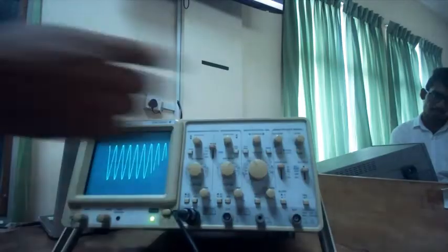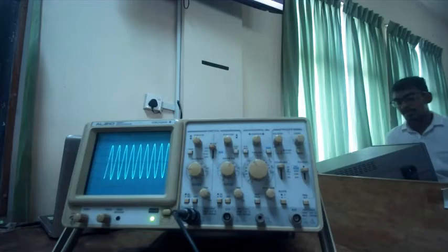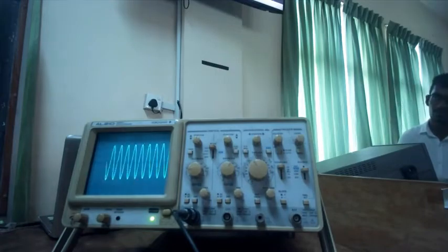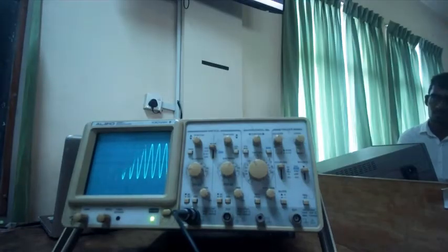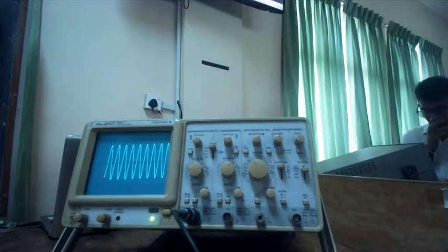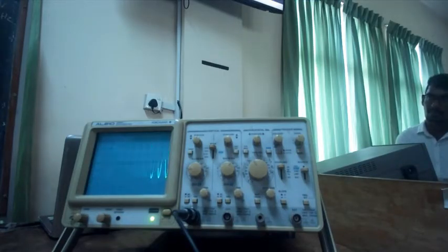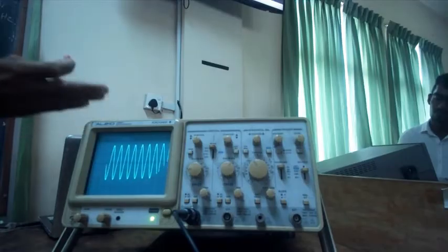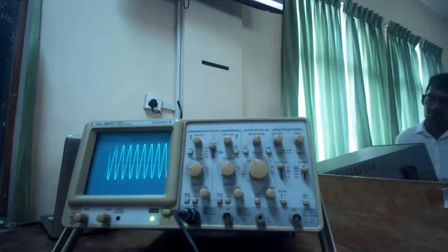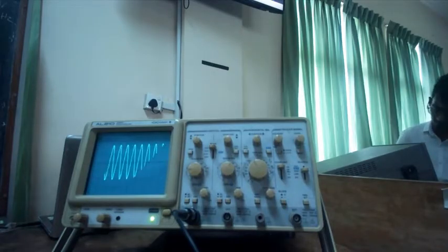Now there's another one, the trigger source, whether it is channel 1, channel 2, or line. Line means the 50 Hz signal. The oscilloscope is powered by the line, 50 Hz, 240 volts, an AC signal. So you look at this 50 Hz signal, and you make sure you attenuate it so that this level corresponds to the maximum and minimum levels of this screen. So let's say 0, -5 and +5, and then you define the value and the slope.